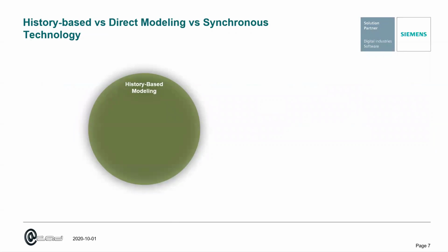Right, so over here, we will do a comparison between the 3 different approaches being used by 3D CAD tools with regards to 3D modeling. So the first one we have over here is the history-based approach, or we can also call it history-based modeling, where a design is created based on features, after features. And in order to create all these features, most of the time we will be spending time on 2D sketches together with putting in all the 2D constraints like dimensions to help us define the size and the shape of the design we need.